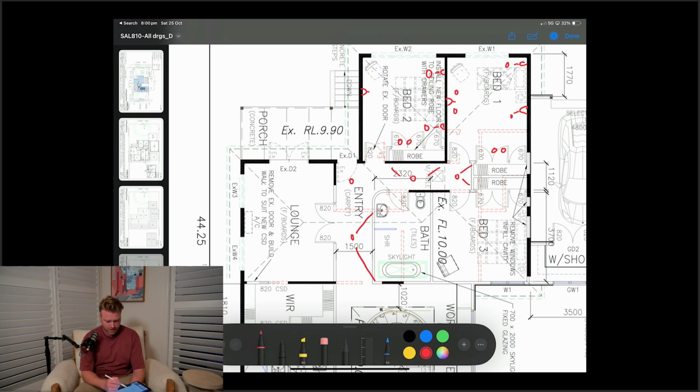So this lounge slash master space that will eventually have a master bed, I'd probably consider doing PowerPoint there, PowerPoint there. So if you wanted that bed there, that'd be fine, because this door can shut. This will have a TV unit here, so there'll be some power there, but I'd probably be doing power in this corner. I probably wouldn't bother about this corner. And then I'm going to do one big central light in this room here.